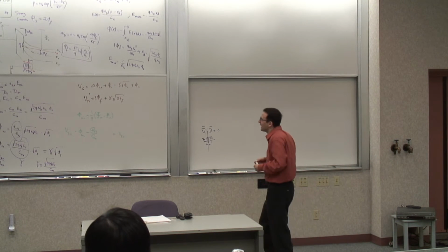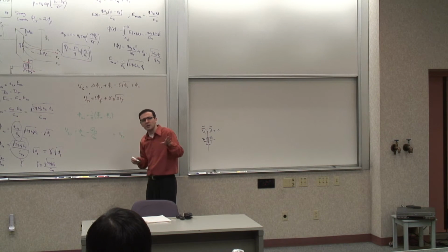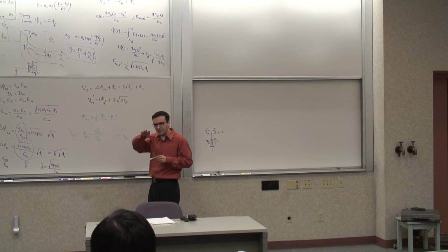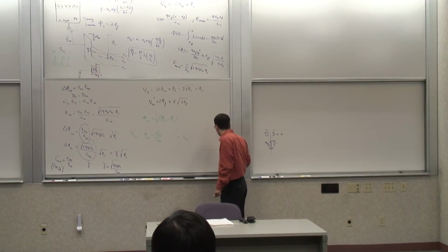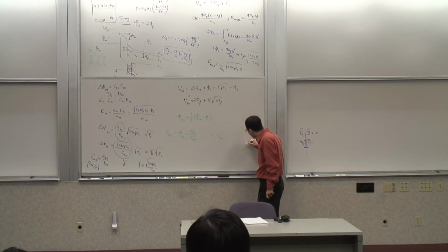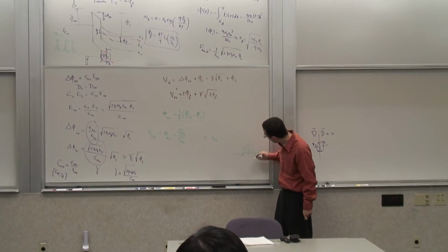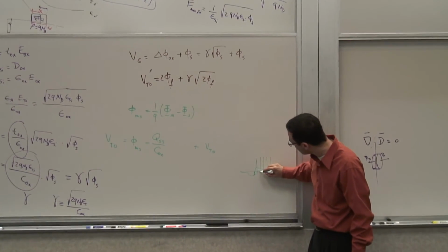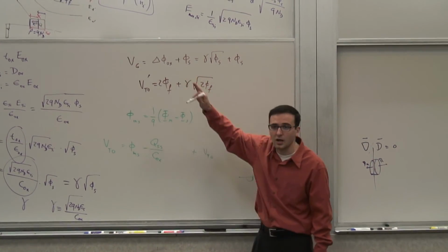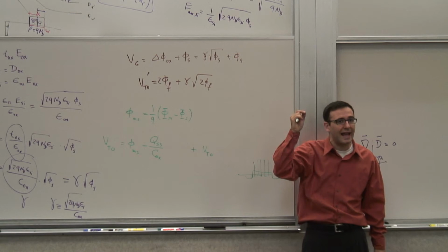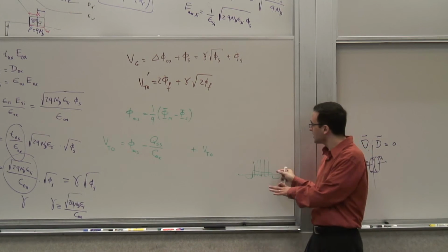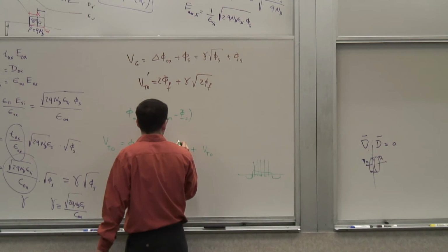Now, that's called an implant charge. When we see the fabrication, you will see how that works. But basically the idea is that you introduce additional ions through ion implantation. You accelerate ions and put them inside the channel, right under the oxide. You implant additional charge at the surface, just enough to compensate by the right amount.